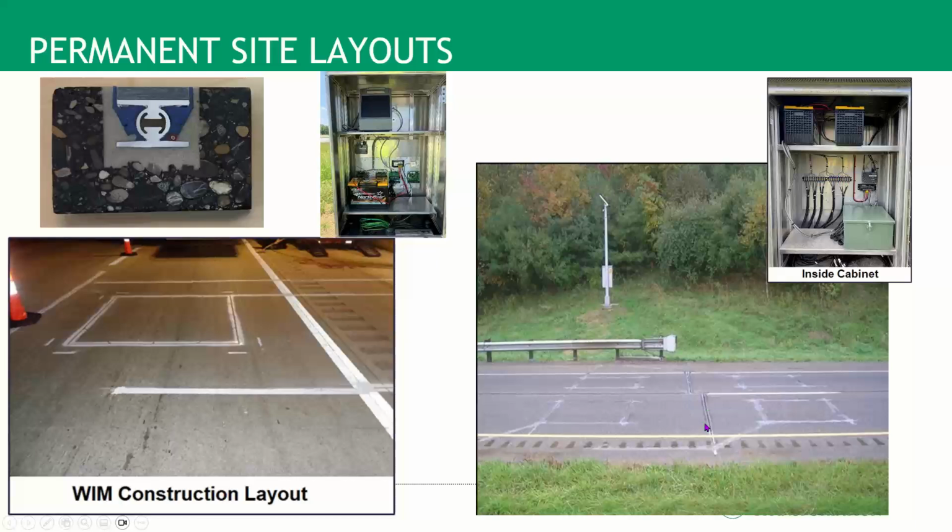Piezos are installed with grout. We all know Ohio has freeze-thaw. The piezo might work great, but it gets damaged by freeze-thaw and the grout. It's usually the grout and the pavement around it that fails, and that's when we lose our piezo. So let's say we now have just a loop and a loop. Now we can still, remember that little loop diagram with the yellow race car running by? We can still tell how fast someone's going.